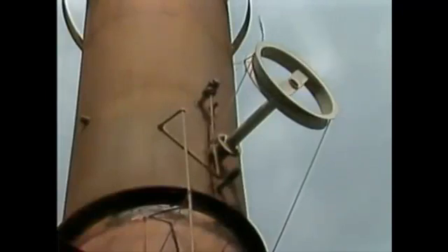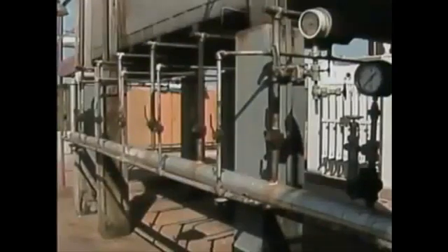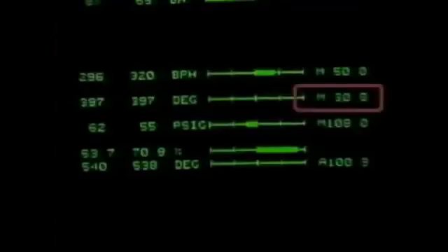Basically, the airflow conditions in a furnace are controlled by coordinating the positions of the stack damper and the burner air registers. In addition to the airflow conditions, the fuel supply to the burners also has to be controlled. If there's too much fuel, some could be wasted because fuel may leave the furnace without being burned. If there's too little fuel, there's a risk of flameouts and explosions.